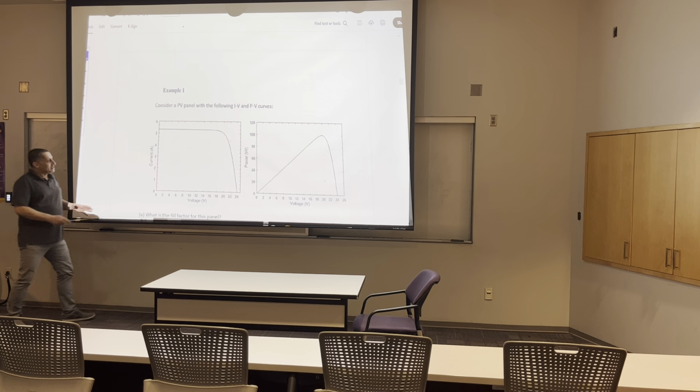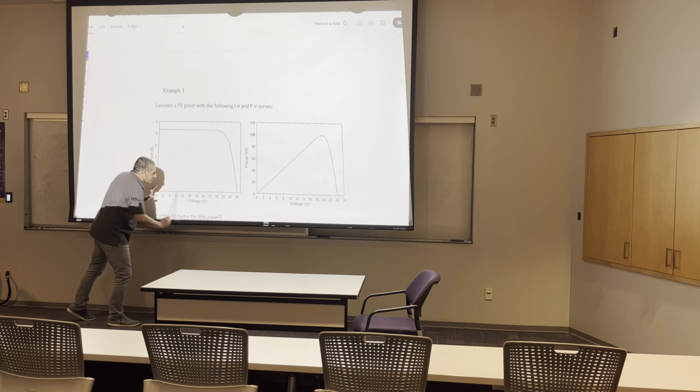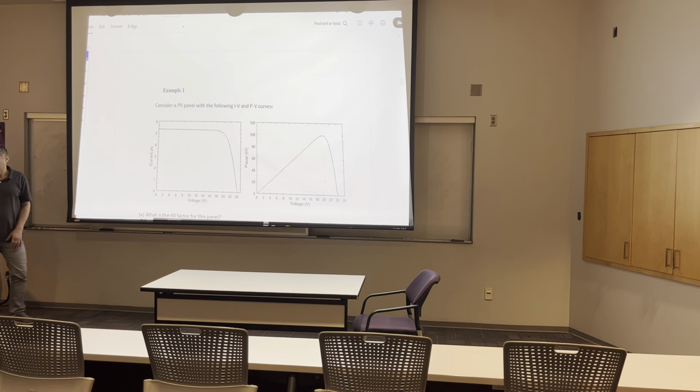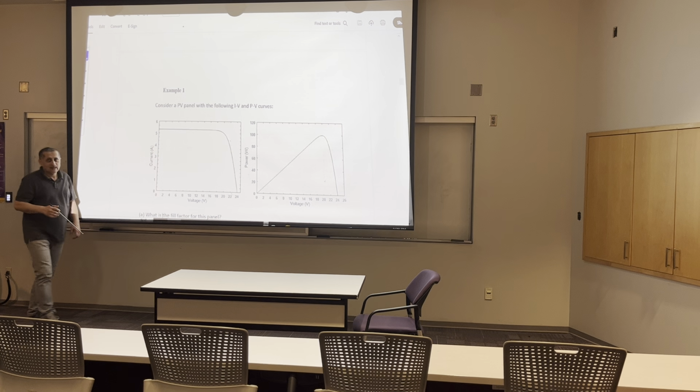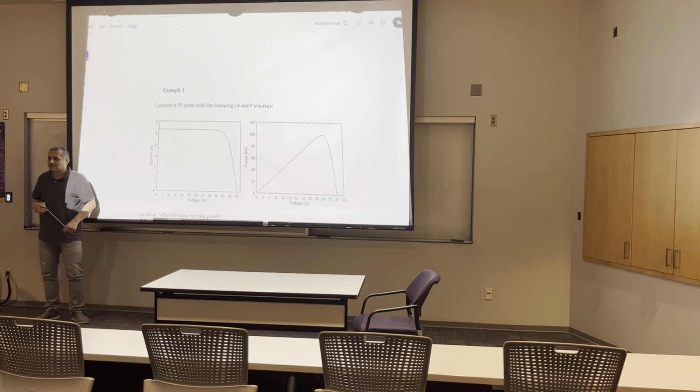This curve is the relation between I and V. It gives the relation between I, generated from the solar cell, and V across the terminals of the solar cell. Look here. When V equals 0, what does it mean? V equal to 0 means short circuit, right?